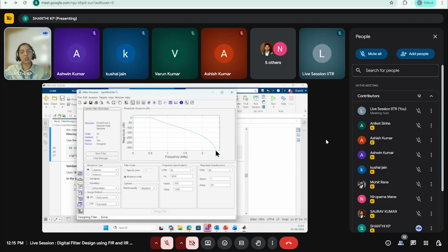So what does this drop mean? Like the peak drop as compared to the FIR filter. This means that the filter strongly suppresses the high frequency noise, which is exactly the requirement behind our design, right? So seeing the magnitude response, we can confirm that the IIR filter should reduce the high frequency electrical noise, which is beyond 1 kilohertz, and will retain the low frequency vibration content, which is below 500 hertz.